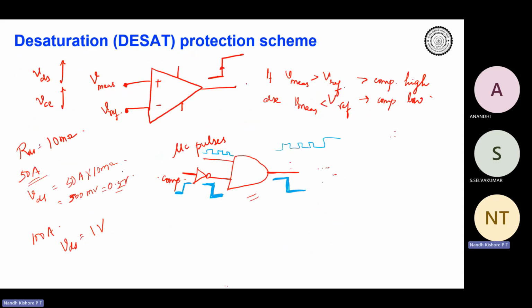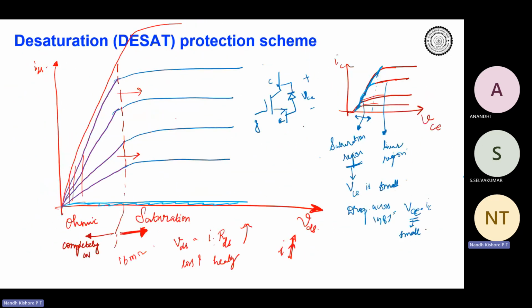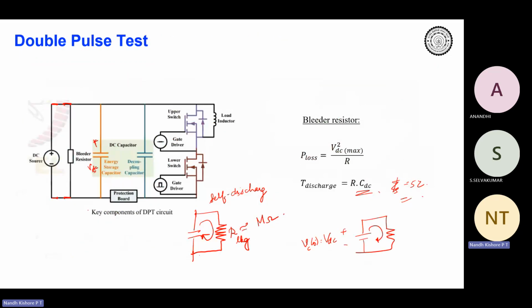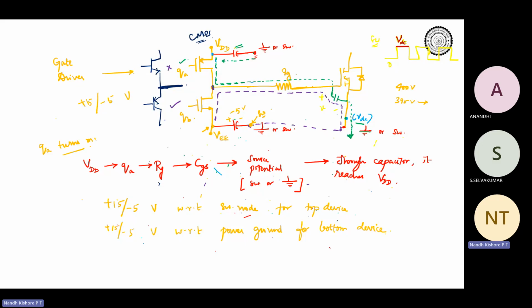The other way, the simplest way, is you take a multimeter, put it in resistance mode and measure across the device. Ideally, when the device is in off state, the resistance should be in mega ohms. The multimeter will show OL, overload. If the multimeter shows a direct short, that is, if you check in continuity mode it will beep, it means the device is gone.